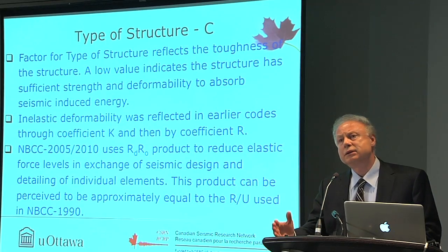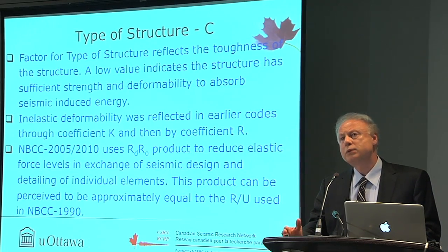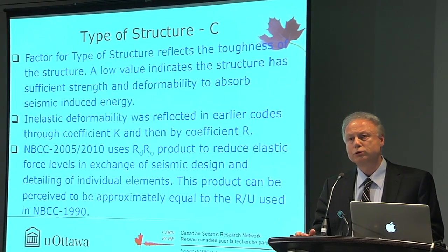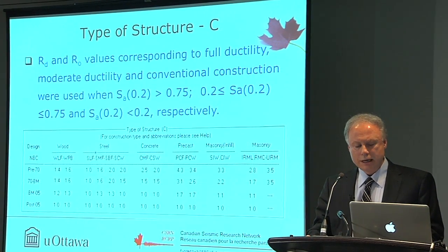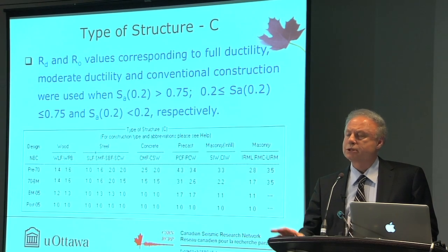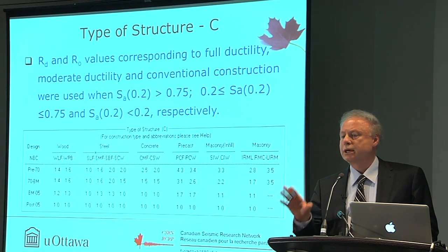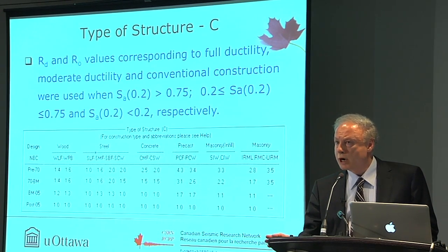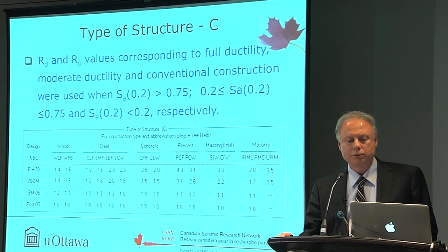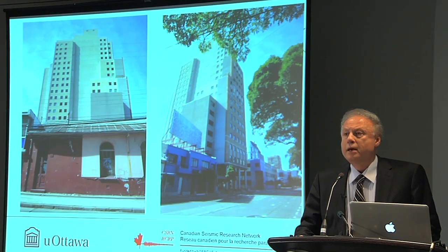And the differences in the way we introduce the C factor in older codes and newer codes have now been recognized, and for different types of framing systems having different ductility and detailing requirements implemented over the years, these are introduced in this table in a very simple manner for rapid screening through factor C.